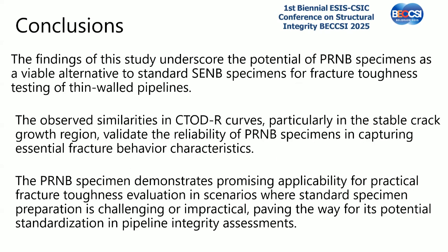The observation of similarities in J-R curves, particularly in the stable crack growth region, validates the reliability of this pipe specimen in capturing essential fracture behavior. The pipe ring notch bending specimen demonstrates promising applicability for practical fracture toughness evaluation in scenarios where standard specimen preparation is impractical or impossible. And I hope that in future we will make one step forward to standardization of